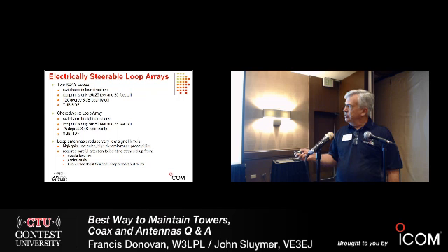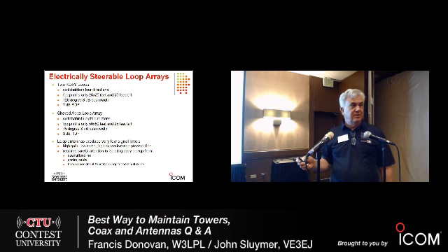K9AY loops. I'll show you a photograph of one. It's about the smallest of the steerable loop arrays. Only 25 feet by 25 feet and only 25 feet tall. So it takes very little space at all. Has reasonably good RDF. Notice its beam width is quite broad, 120 degrees. It's a little bit broader than a Foursquare for anybody who's used a Foursquare. Foursquare has a broad pattern off the front, and so does this antenna.